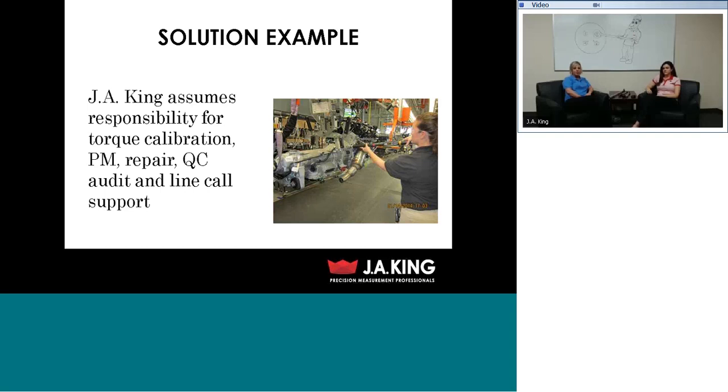With our embedded services, the customer only needs to contain 30 units. However, without the quality control, the operator still receiving an okay reading could have left this until their tool scheduled calibration due date. If the issue occurred early in the calibration cycle, this could have resulted in a significantly larger issue. So essentially, without a robust quality control program, say that the tool had just been calibrated 4 weeks ago and it was on a 6-month interval, you may not have even known that that tool was out of tolerance for 5 more months. That's right. Yeah, that's a great example.